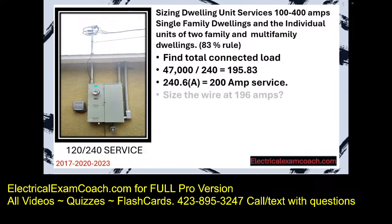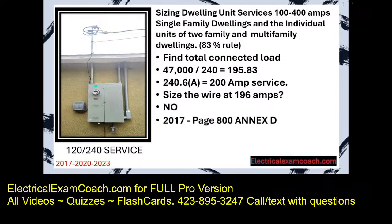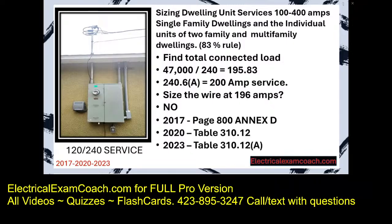Now the next step normally would be to size the wire at 196 amps, right? That's our known load. We can just follow our normal ampacity rules. Well, not with services that are in between 1 and 400 amps. And let me show you what I mean. Let's all head to page 800 if you're in the 2017, this table if you're in the 2020, and this table if you're in the 2023.